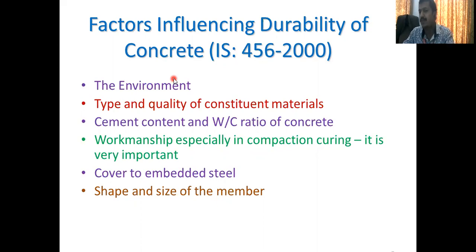Then cement content and water cement ratio of the concrete, a very important one. If it is taken properly in your concrete mix design, you will have a good durable structure. But if you are taking it in excess or in low or in any wrong proportion, then definitely it will influence the durability. Okay, how is it there?